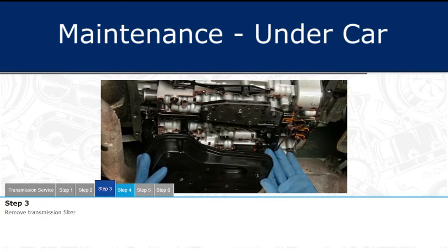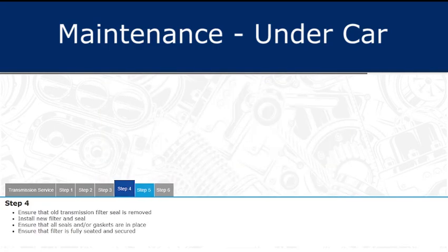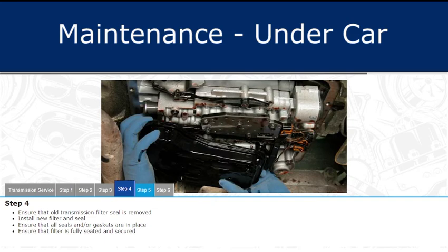Remove the transmission filter. Ensure that the old transmission filter seal is removed. Then install the new filter and seal. Ensure that all seals and gaskets are in place and that the filter is fully seated and secured.